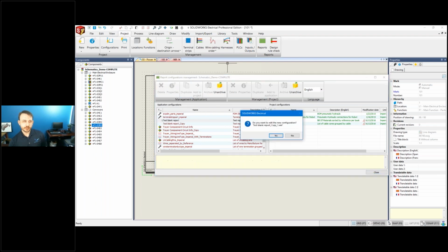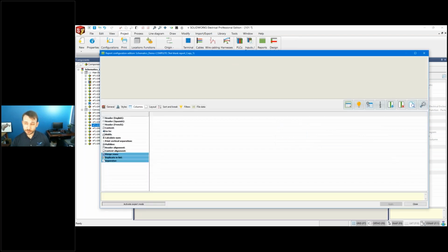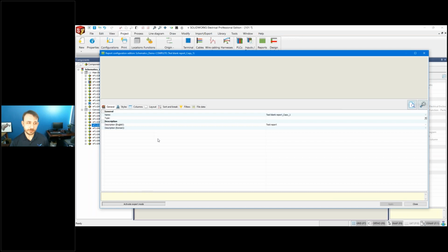Okay. So one thing to think about, I probably should have mentioned this earlier, is anytime we're going to make a change to a report, especially if you're going to change one of the default reports, I tell people to duplicate it first. The reason being is when I go to do an update, if I make my change, and I need to go from 2020 to 2021 in October, any of my defaultly named reports could potentially be overwritten during that update process.